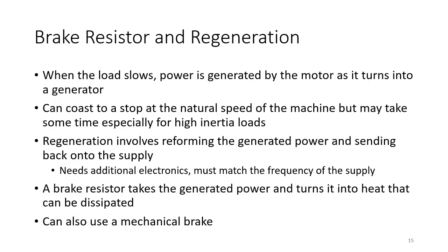Now, when the VFD is turned off or slowed down, the motor continues to run and it continues to be controlled by its load. That load could be significant. As the motor slows down, power is generated by the motor because the motor turns into a generator. What you could do is just let the system coast to a stop at whatever speed it takes. But that could be some time.